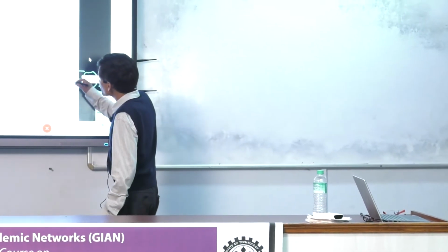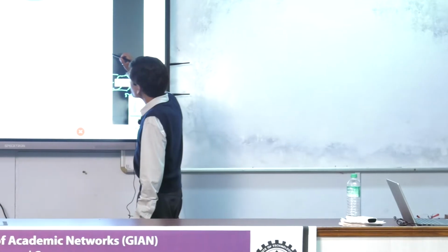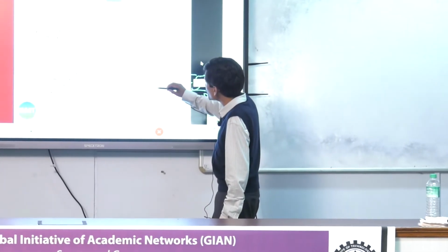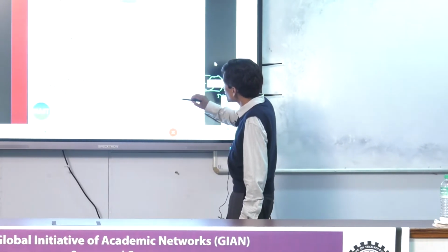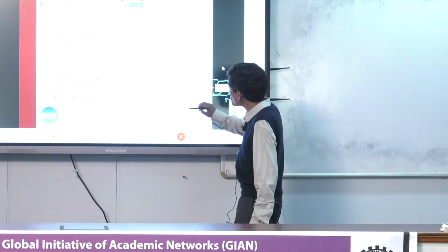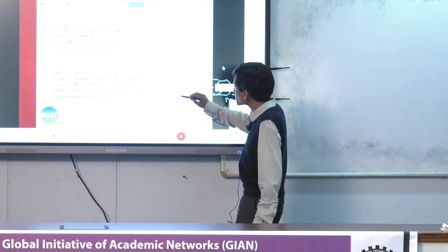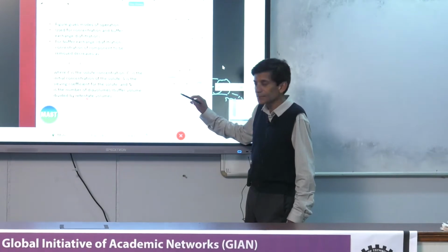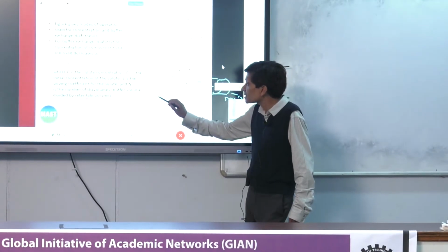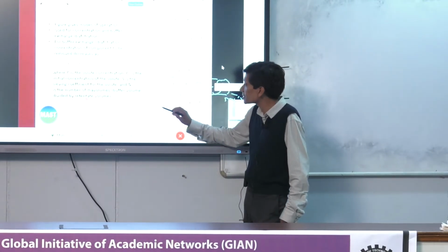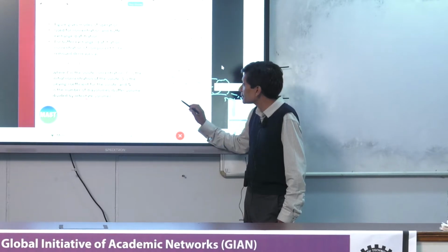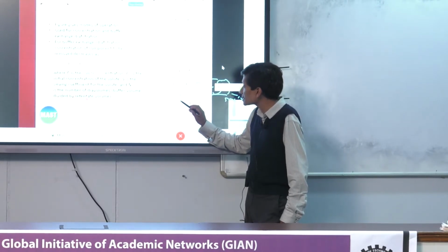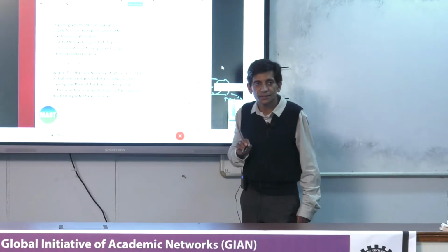So here's your ultrafiltration membrane, and here is the recycle tank that has your feed. So you're running this in concentration mode, you're removing permeate, you're concentrating your protein here, okay? But in the meantime, you have another buffer here, this is your second buffer, that you're adding to the recycle tank at the same rate at which you remove filtrate.